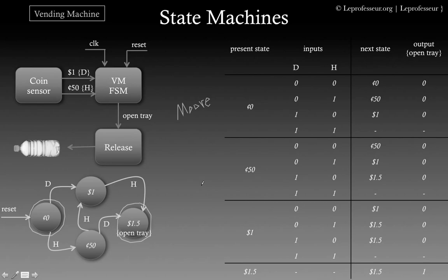Now let's try to understand how we can put coding onto these states. As we know, we have four states. Now in binary, how many minimum flip-flops would be needed if we want to use binary encoding? So 4 is equal to 2 to the power 2, and in binary we have base 2, 0 and 1, so we need at least 2 flip-flops.